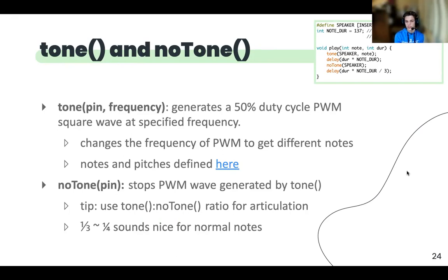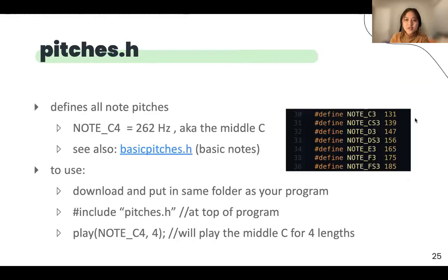We have some little code in the top right, which is an example of what we want to do with this, which is creating a play function where we use tone, then delay, then noTone, and then another delay, which will help us in this project for creating music.